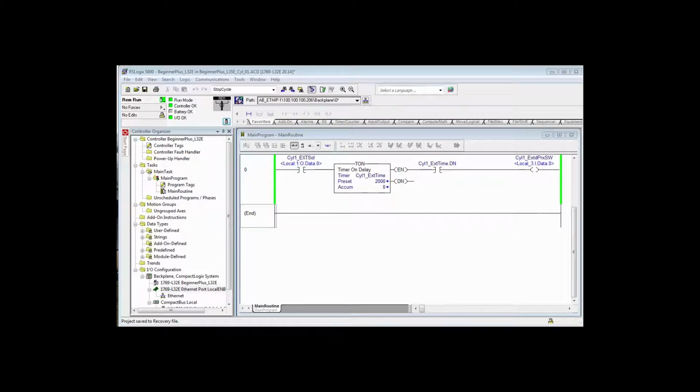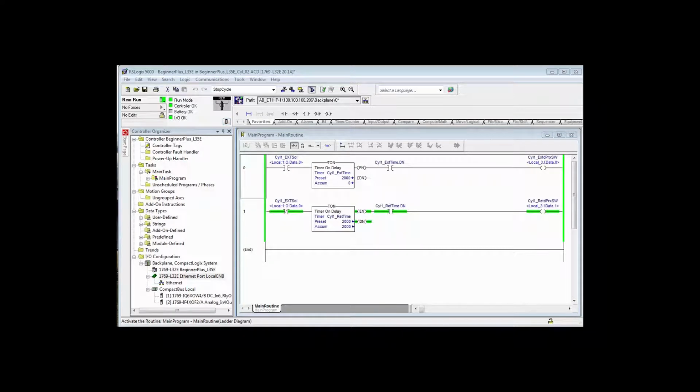Personally, when I work on a process, I, for the most part, get right in their face that I want a sensor on both ends. What they'll do to save a few bucks is only put a sensor on one end of the cylinder. Now, in some cases, 2 sensors won't even fit on the cylinder. I've seen that hundreds of times where the stroke is so short or the space is so limited, you cannot put 2 sensors in there. This little simple rung here is: energize the solenoid. 2 seconds later, you're simulating that the cylinder is extended. That's simple. The nice thing about virtual devices is the cost is minimal and space is abundant.